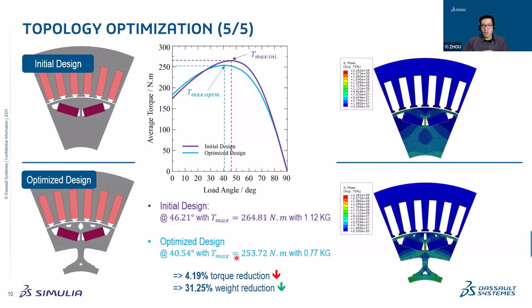Speaking to the structure side, we can also see that even with such a reduction, we didn't lose the strength of the rotor. The magnet is still under the 100 megapascal limit, and the rotor is under the 300 megapascal limit at the maximum speed. That means we try to make full use of the region of the part of the rotor, and just leave out the useless part.